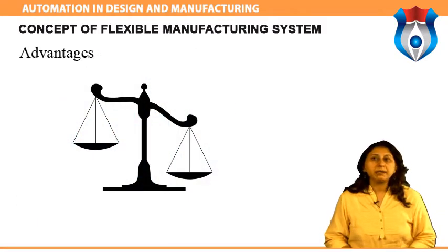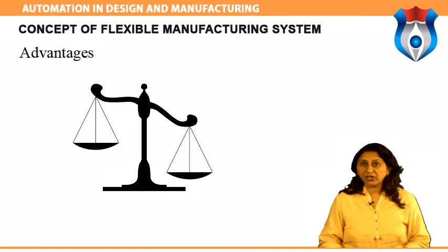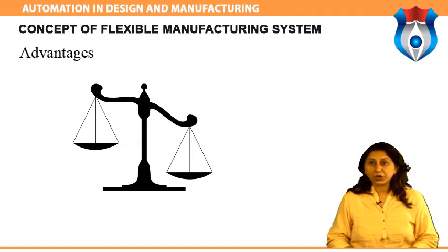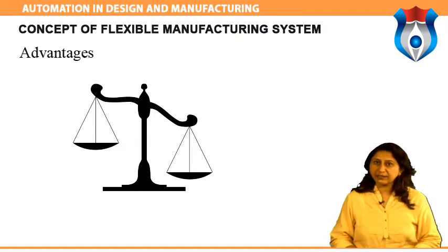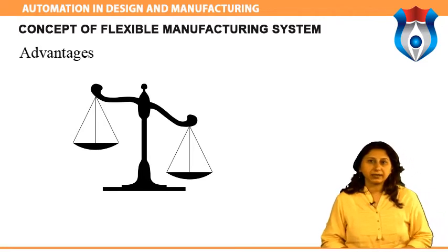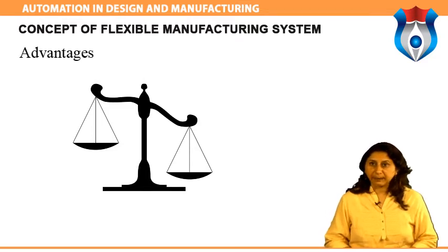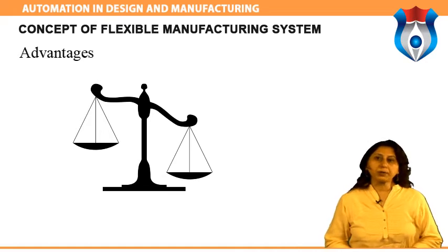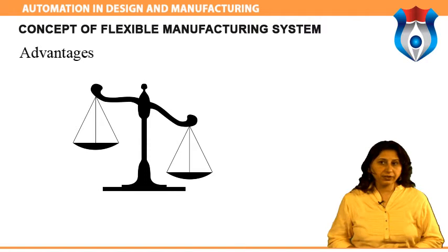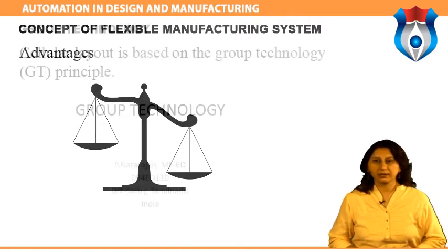Disadvantages: limited ability to adapt to changes in product or product mix. For example, machines are of limited capacity and the tooling necessary for products, even of the same family, is not always feasible in a given FMS. Substantial pre-planning activity. Expensive, costing millions of dollars. Technological problems of exact component positioning and precise timing necessary to process a component.